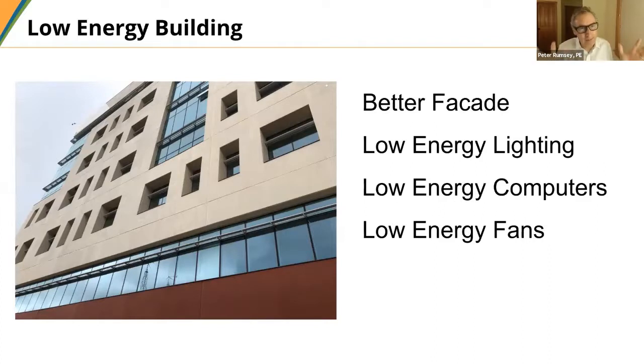You still have the glass, but when it's recessed, the direct sun doesn't hit it. You can also see the light shelf, these horizontal lines, that bounces the daylight into the space. So they get the natural light without the glare and brightness that makes people squint, and then they have to pull the shades, and then lights have to turn up.